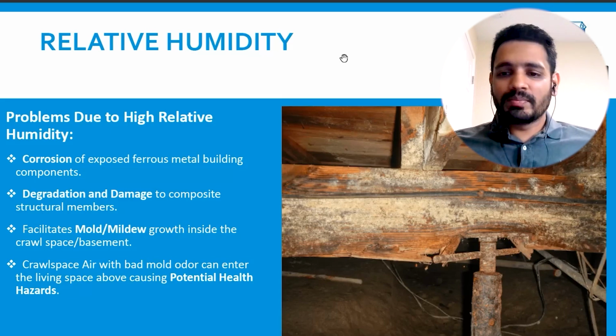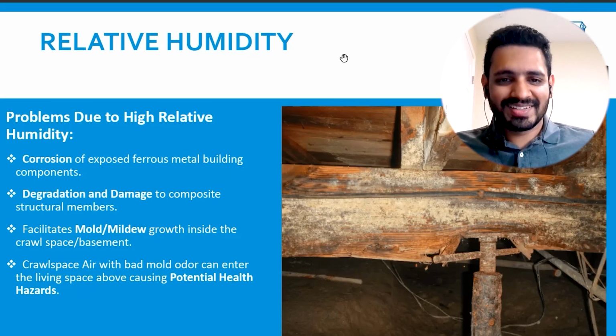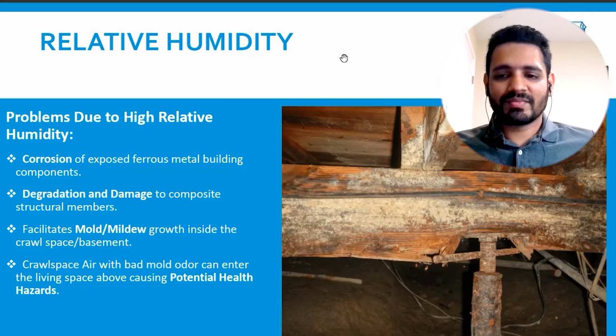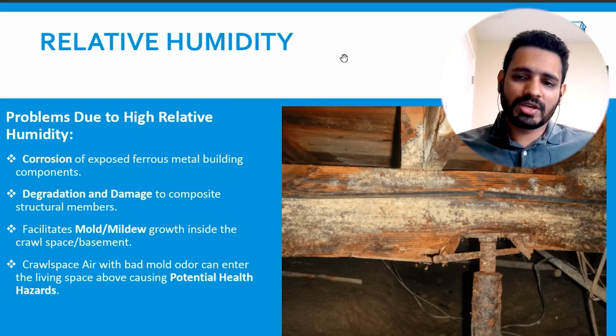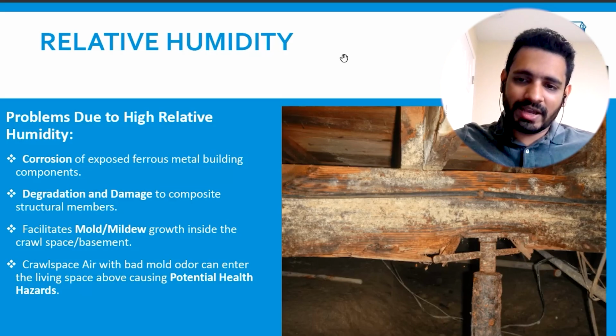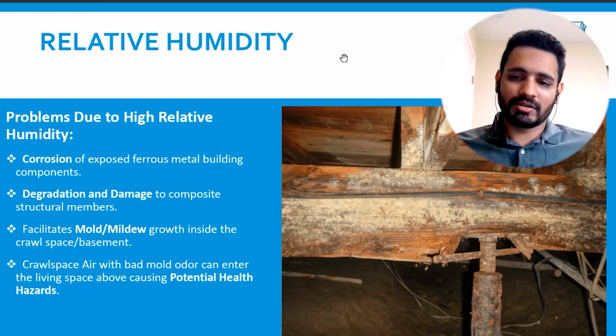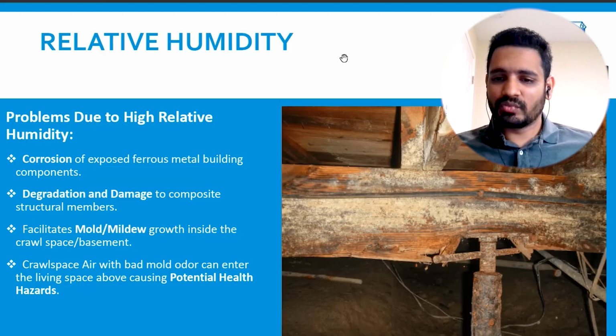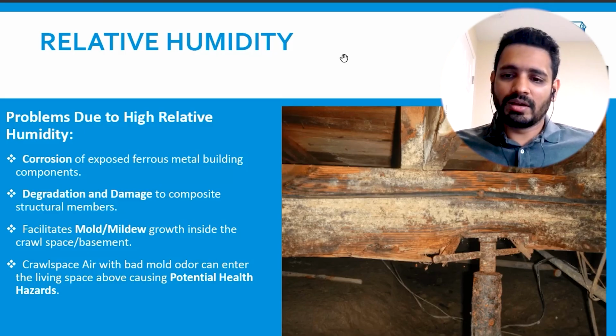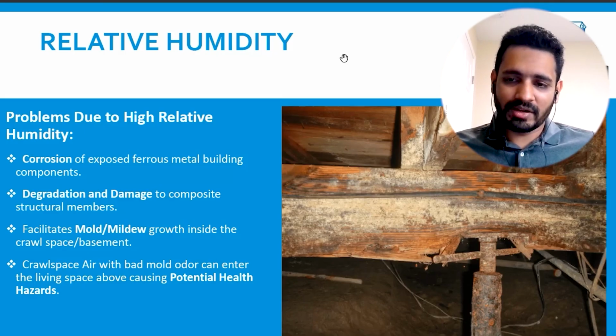So people thought, okay. And I assume that they put the jack there so they can adjust the settlement in future. Exactly. And the wood posts do the same thing. It's easy to swap out a wood post, but the metal jacks, you can actually crank them. You can actually adjust them in place as long as they have a corrosion protection sleeve and they're not significantly corroded. And most of these jacks will have a base plate that is corroded, would not be properly fastened or bolted down to the concrete pier, or may not be connected to the wood beam that it's supporting.